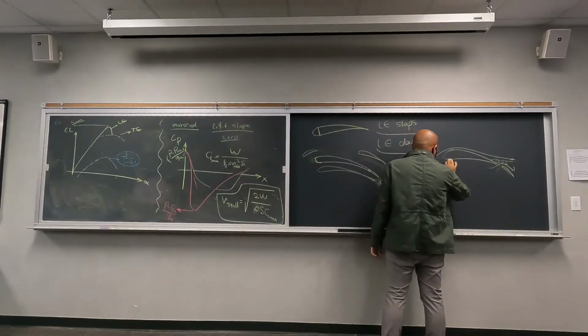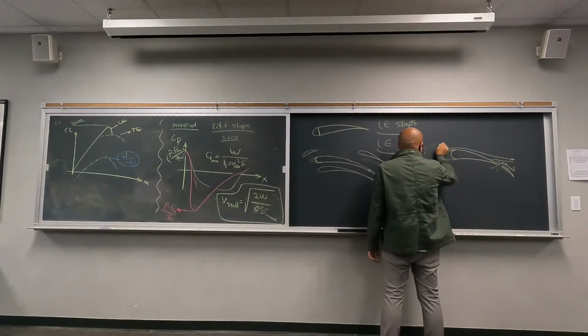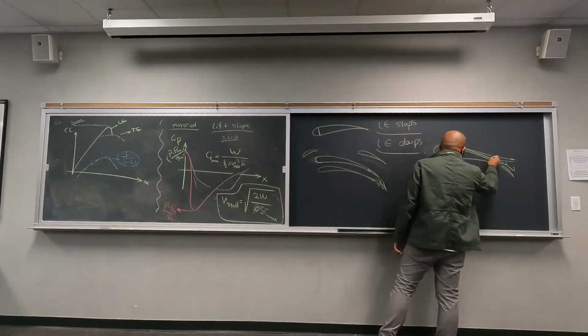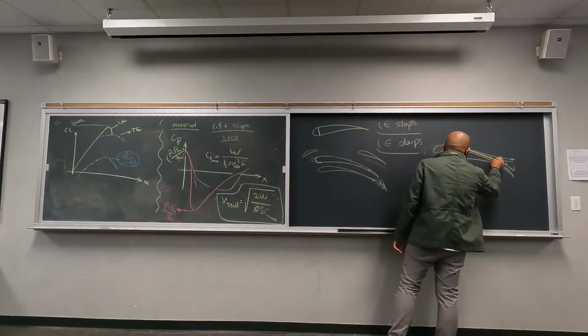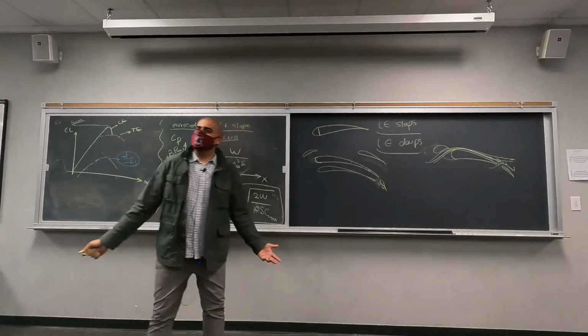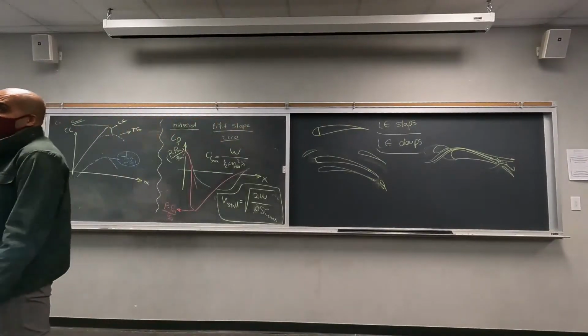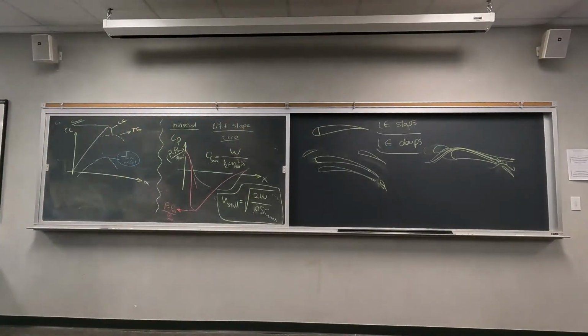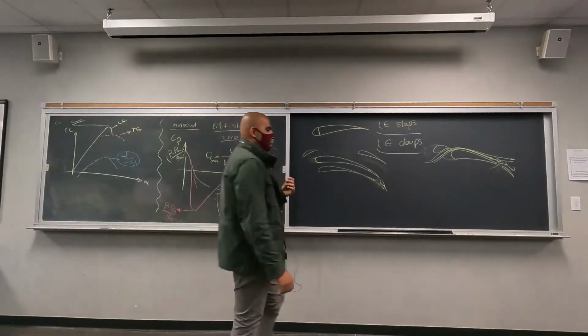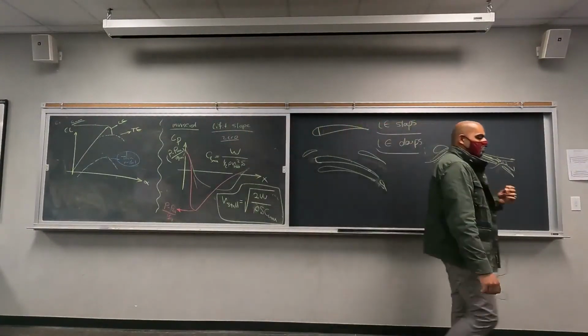you release whatever that is in front to move forward, you are going to push some streamlines to stick to the airfoil. That's how you affect the flow pattern, right? You are going to minimize the effects of viscosity by reducing the boundary layer thickness and effectively reducing the flow separation, or delaying the flow separation.